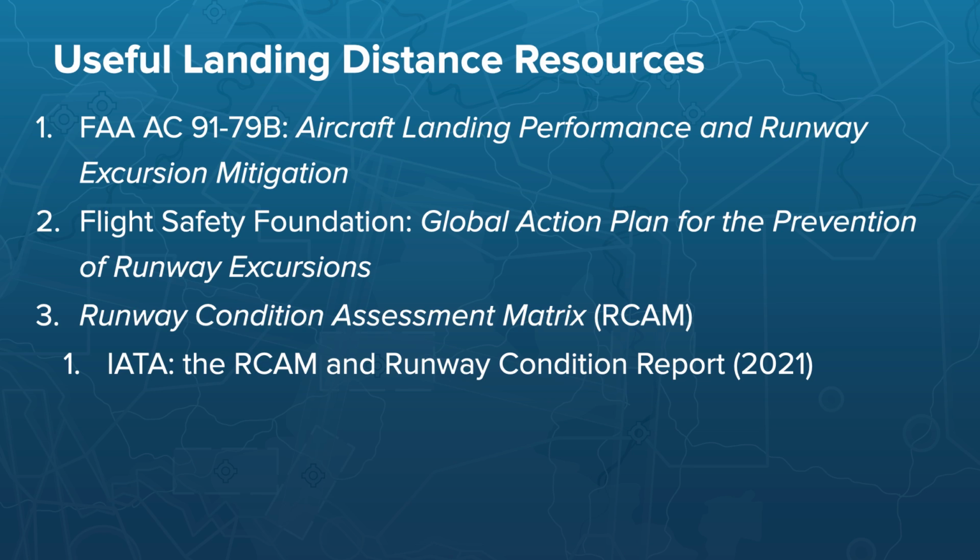And as you will see in the examples that we'll show in a little bit, we have introduced a phase of flight concept allowing pre-flight or dispatch landing distance calculations, as well as in-flight or landing distance at time of arrival assessments. In Europe, the latter is referred to as LDTA, landing distance at time of arrival, and it is a required landing distance assessment if the weather or runway conditions deteriorated from the conditions used during the pre-flight landing distance assessment. So we have chosen to use the LDTA abbreviation in in-flight landing distance calculations within the app, as you will see. I highly recommend reading this AC. It is really chock full of good information on aircraft landing performance calculations.